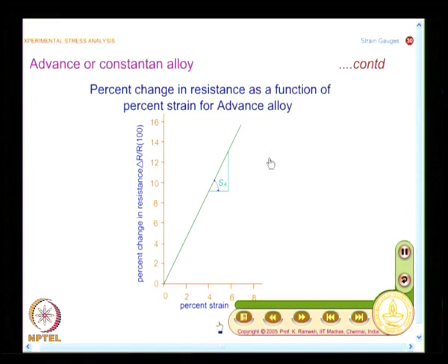If you look at the initial stages of engineering development, people focused more on worrying about plastic deformation. Now, with advancements in fracture mechanics, people worry about normal strains. They are not worried about excessive plastic deformation, because now we have optimized to the extent we want to make the maximum out of the material, and we also bring in inherent flaws. So, now the strain measurement domain is different, but when you are looking at the technology, it is useful for both elastic and plastic region. That is the key point here. So, it varies from 0 to 8%.